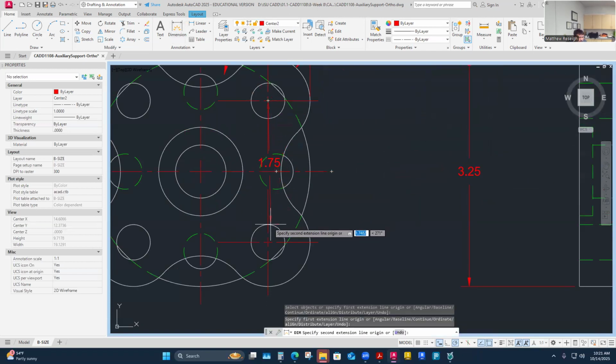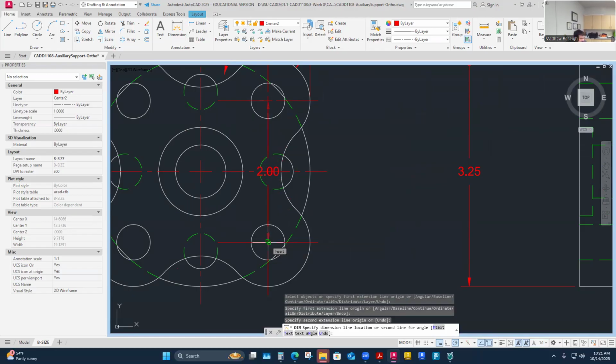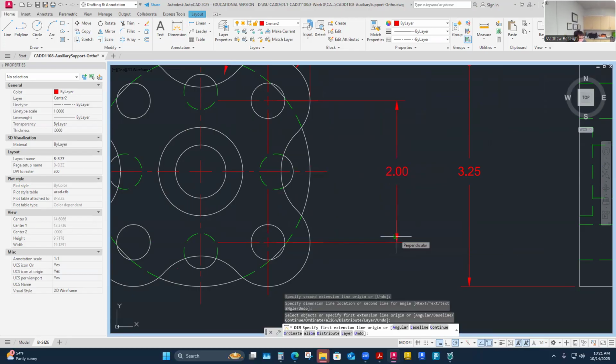This could be a pretty good candidate, because we always usually like to know, even though I don't put them on all my prints, but generally when you have hole to hole, you'll like to know the center to center location of holes. So that's maybe one dimension, but that's really based off from hole to hole. It doesn't come from a control necessarily, right? That's why I sometimes leave it off on my dimensions, unless I know what's being controlled and how critical the hole pattern is. Sometimes I've been omitting it on some of my drawings where I've dimensioned, because this is a great dimension to know, but it's really based off of no control. It's just kind of floating out in space.